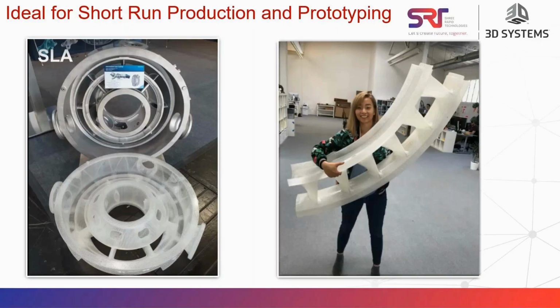So what SLA technology gives you is thermal stability. Compared to powder bed technology, which normally involves binders and a heat process, it may shrink a lot compared to SLA technology. What we use is an ultra low shrinkage epoxy based resin. It is cured by UV laser, and it is not a solid structure. It is 90% hollow, so it is dimensionally stable. Actually it's a cold process, so you don't need to worry about surface quality or maintaining temperature. So this is the advantage of SLA QuickCast patterns.